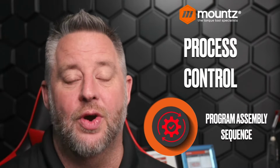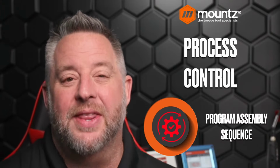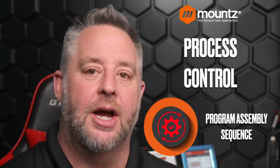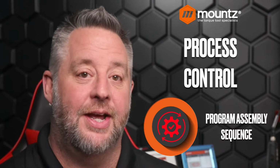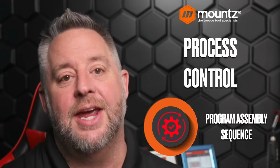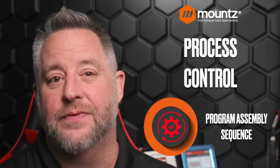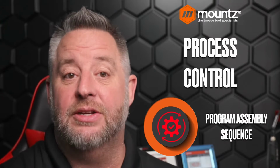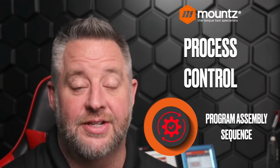Which leads us to our second method here, which is our process control. And this is creating a programmed assembly sequence of our fasteners. And again, that sequence can be different preset values, different torques, and possibly different bits that can be used within the process itself.